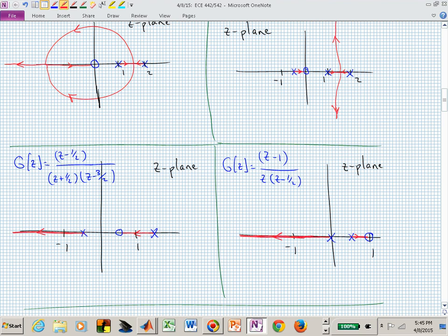And do you see that in the lower row of examples, the one on the right, look at how the root locus goes to the right, and the one on the left, on the rightmost section or branch of the root locus, it goes to the left. We start these root locus diagrams at the x's, or at the open loop poles, and we terminate on finite zeros or infinite zeros with the branches. We're approaching infinite zeros or finite zeros with these root locus branches.